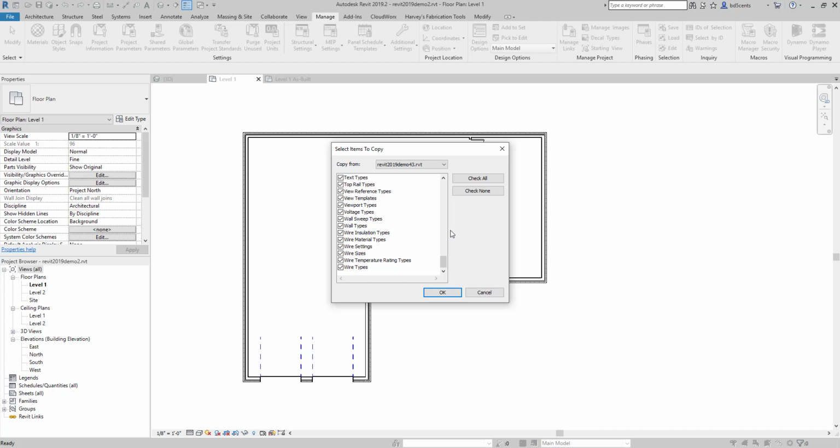It's essentially stealing from other Revit projects. So if you have a Revit file that was completed previously, you can steal the following elements. You can steal drawing sheets, drafting views, ones with AutoCAD files in them, schedules, and legends. So if you did a perfect equipment schedule in a past project, you can steal it and use it in a current project. The actual equipment families will of course not come over, just the parameters and setup.